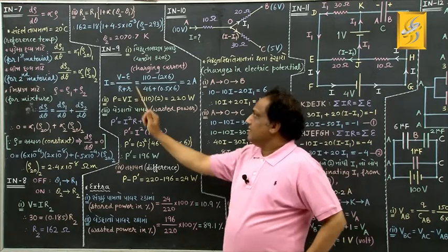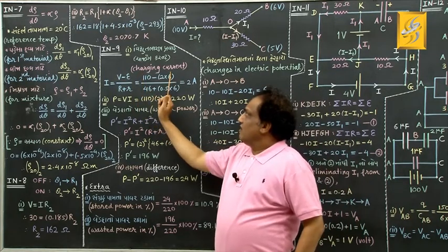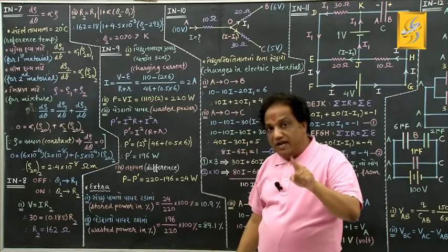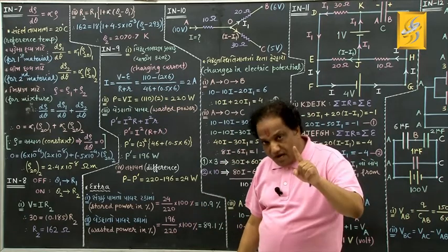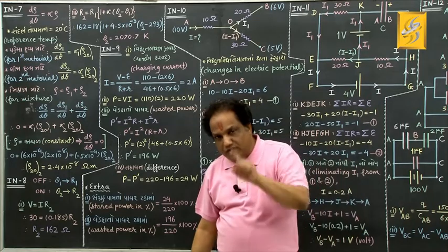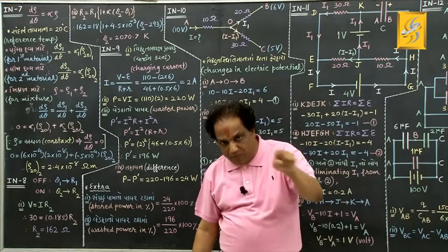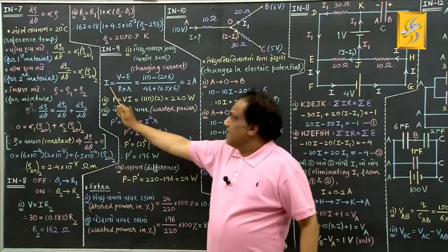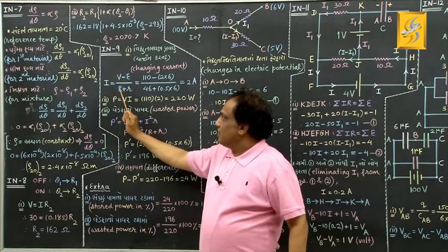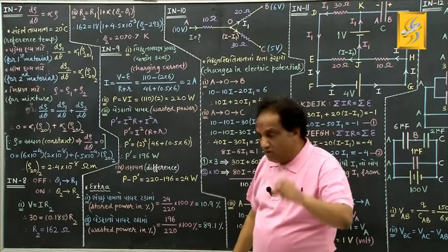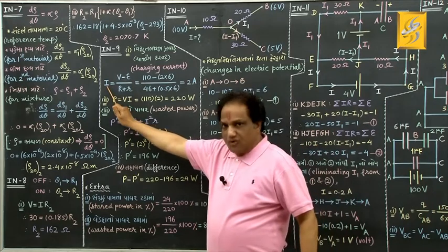Look. Come on. Formula for charging current in case of the charging process of a lead storage cell. We had derived it in the theoretical part. What was that formula? Capital I equals capital V minus capital E upon capital R plus small r. The same formula is written here, I equals V minus E upon R plus r. Just give me identification of each symbol. This is the charging current. Okay.